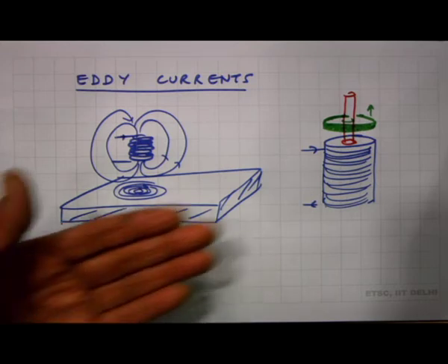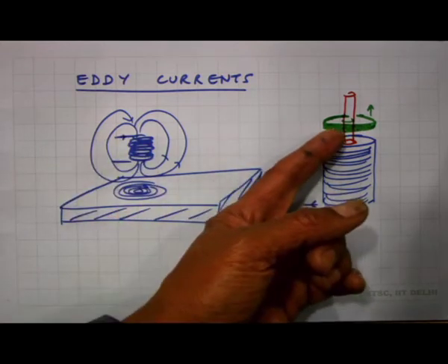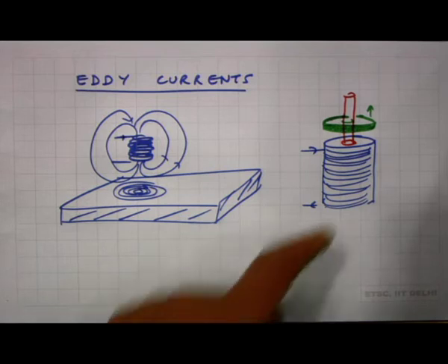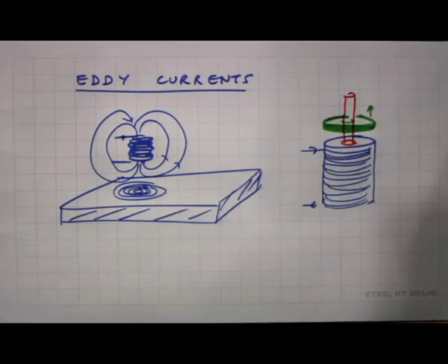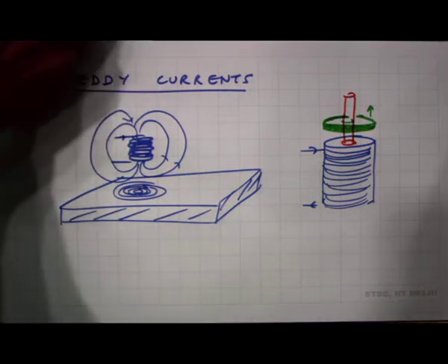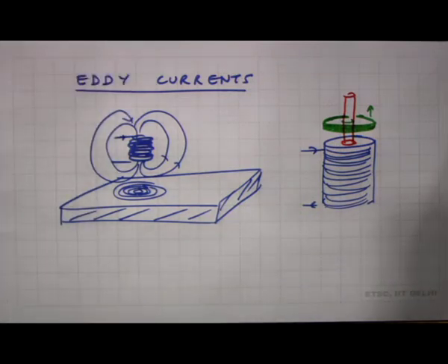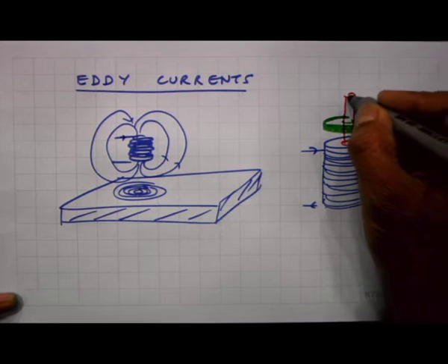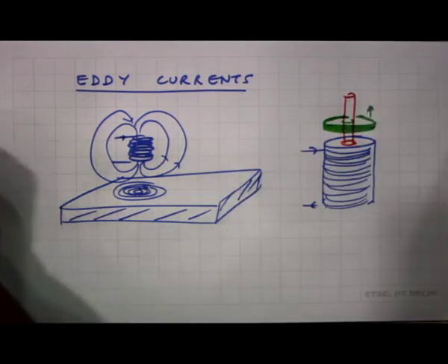So, these are the currents that will get generated within the solid, and this is exactly what is happening in the demonstration that I showed you. There are eddy currents generated in this, and those eddy currents are responsible for the effective magnetic repulsion of the solid with respect to this. Now, in fact, you may have noticed that this was not a solid rod, it consisted of a large number of small rods here.